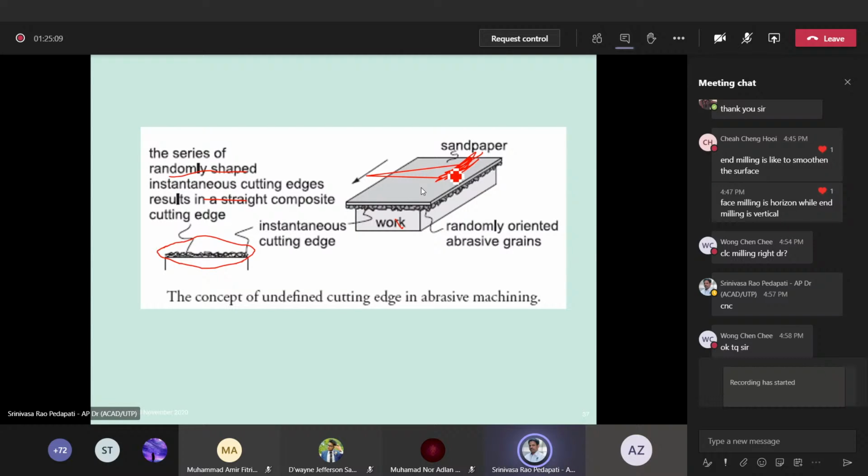If you apply sandpaper on a rough surface to make it smoother, it makes it smoother because of the cutting edges formed by the abrasive particles, which participate as a cutting tool and remove the finest particles from the surface. The finest particles are removed by these abrasive grains. Based on the sandpaper number, say 90 microns, 60 microns, like that, we will have that abrasive particle grain size.